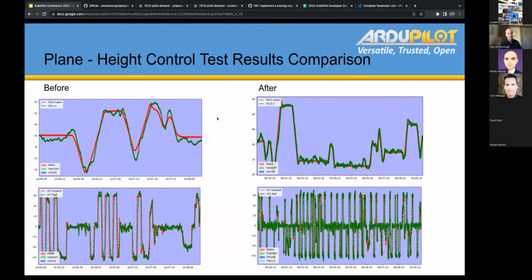That's the next thing I need to do, now start seeing how it works with the flare, and I need to get the little optical flow sensor into that Strix Nano, so I've got a reliable height above ground I can use for the flare maneuver.